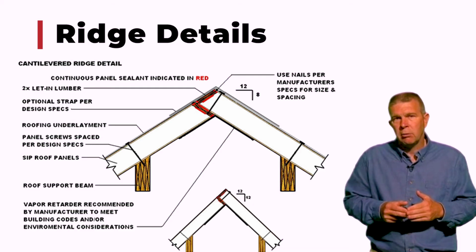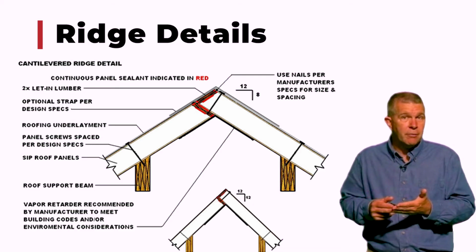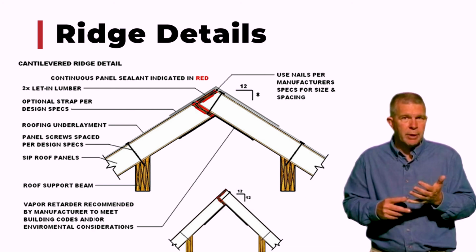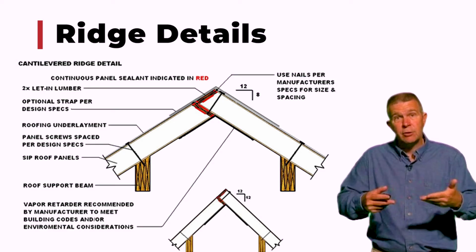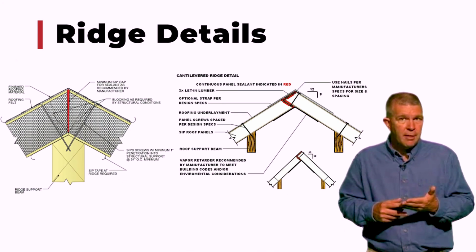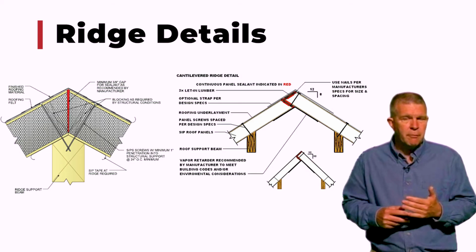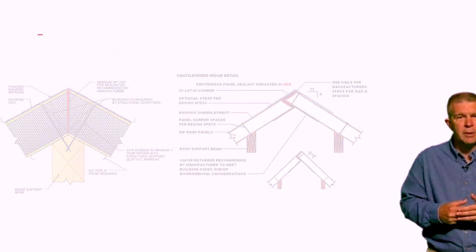This offset ridge detail works very well in not only holding up a roof, but in some cases, once we frame that off, we have a perfect area to incorporate some of the HVAC systems or the electrical components into a conventionally framed false ceiling that works very well to satisfy some of your trade's concerns about working inside of a roof SIP.